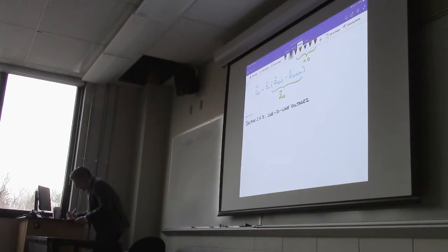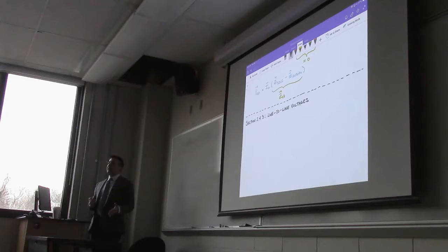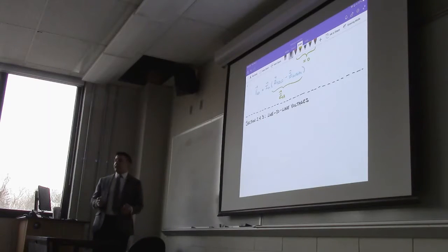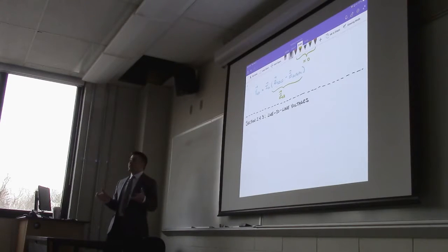So far, we have been dealing only with voltages that look like VAN, VBN. That's called a phase voltage or a line-to-neutral voltage, okay? The line-to-line voltages are like what you would associate if you were trying to measure the voltage across one of the components in a delta device: A to B, B to C, C to A.